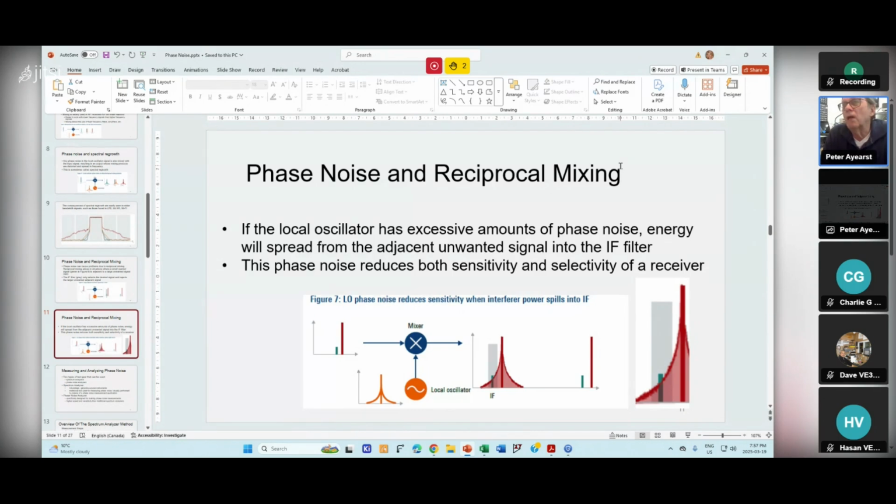So maybe doing some testing on your LO might reveal that you've got a lot of jitter or phase noise going on in that LO. Now, what's causing it could be a crappy component or something else, right? Otherwise, I'm not sure how. Like when Ken asked, how can you tell by listening to it? I'm not sure you can. Maybe you can. I'm not sure though.